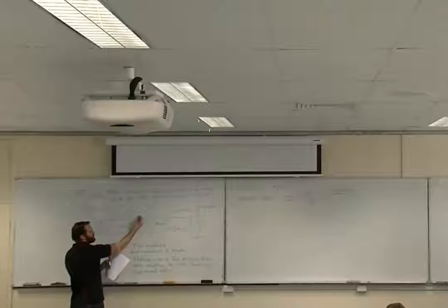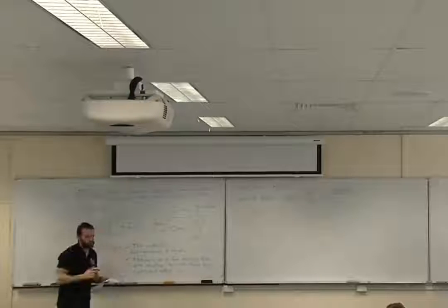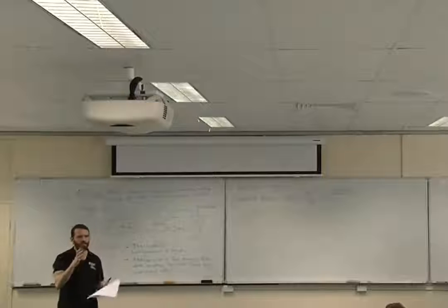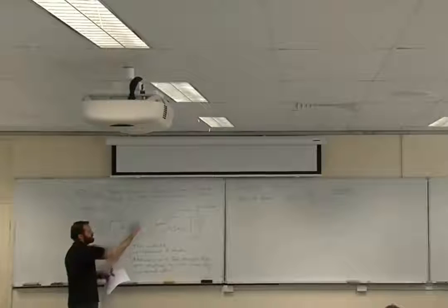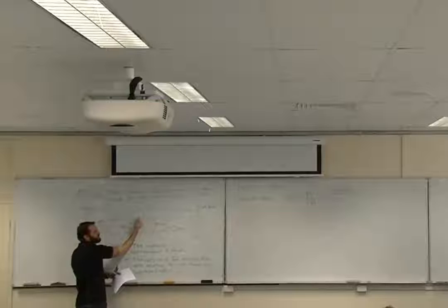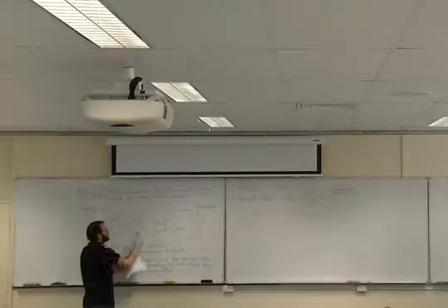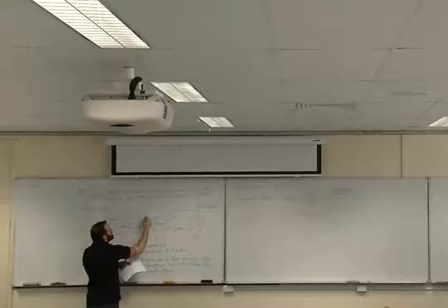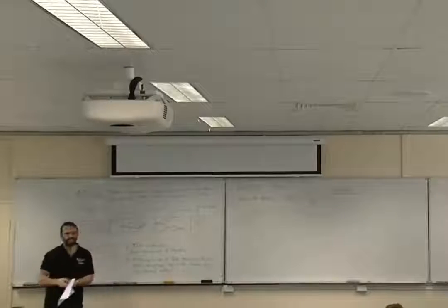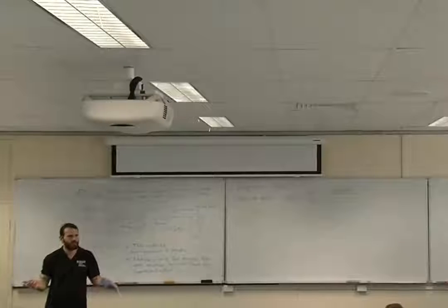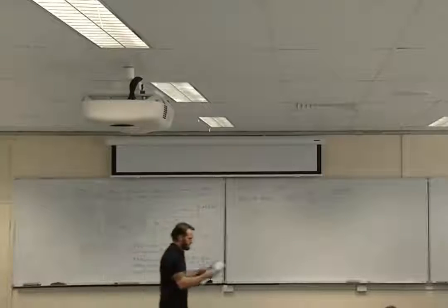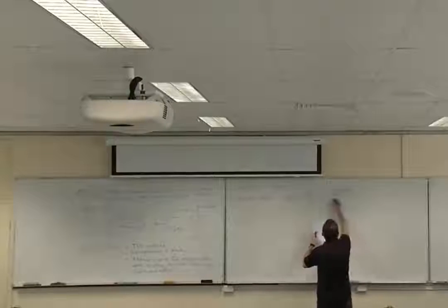So if I'm looking at this hole, take a cross section. It's going to be 100 minus 50, so 25 and 25, times the depth, 25. It's whatever area is left. So the force is being carried over the area contributed by this part and this part. That's the area that carries the force, so that's the area we use for our nominal stress.